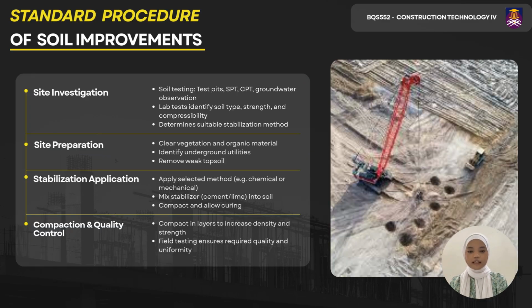This slide shows the standard procedure of soil improvement. First is site investigation. Soil tests such as SPT, CPT, and laboratory tests are carried out to identify the soil type, strength, and groundwater condition. This helps engineers to choose the suitable stabilization method.